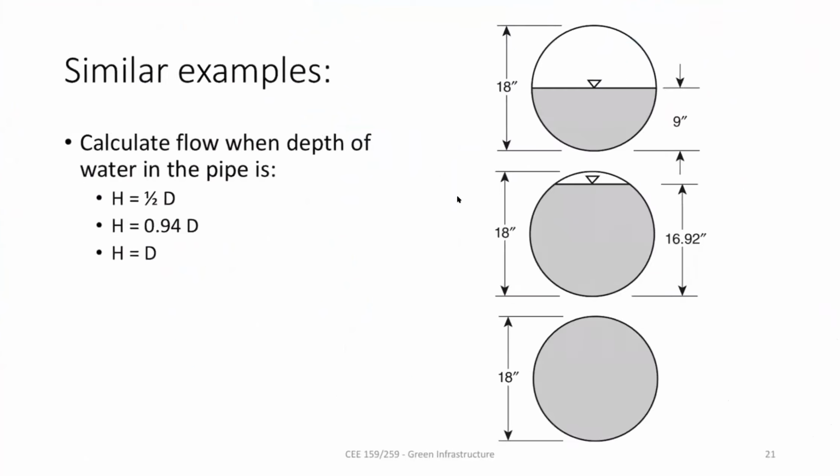Okay, so the last thing of this class before we go for discussion for different examples is stability of a weir wall. Imagine you had this wall, the stream is moving and you put this wall so that water will move and it falls like this if you have an opening. There is always pressure exerted on this wall. That pressure is basically the static pressure that we discussed last class. So I just want to write it here so that you know that this is part of the design. A lot of times the width of that weir depends on how much water you have.